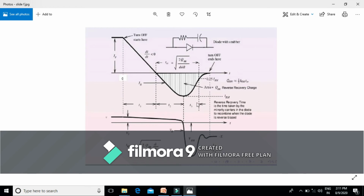Similarly, time TB is measured from the instant when the current reaches from its peak value to 0.25, that is 25% of its peak value. During this interval, charge from the semiconductor layers is removed. This reverse recovery time determines the switching frequency of the circuit, and therefore it is very important to calculate it.